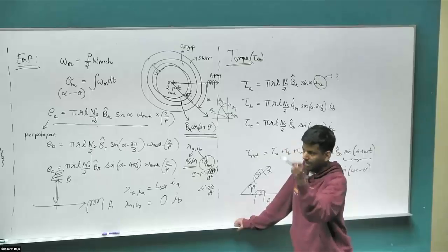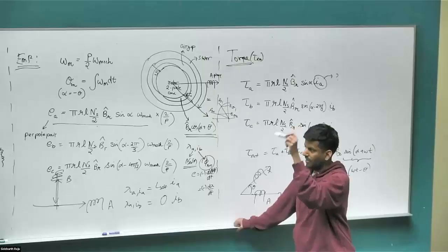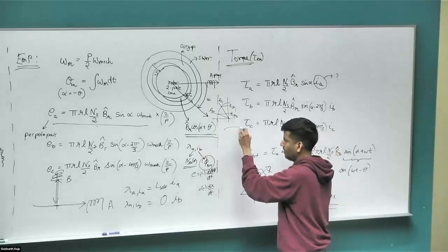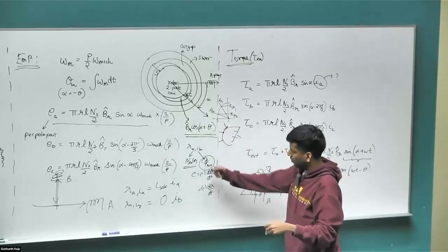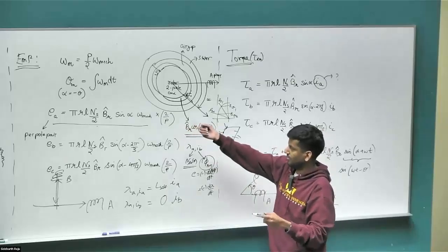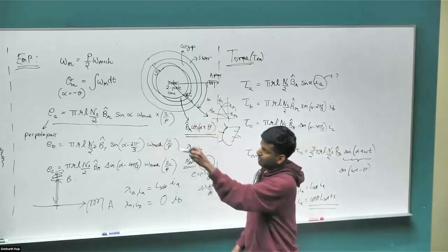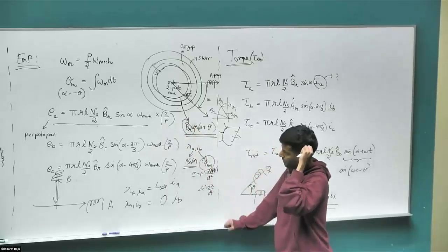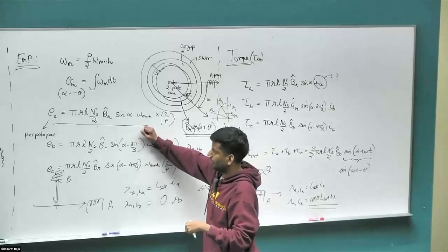And then once we know the magnetic field in the air gap, we can figure out the flux through any particular coil. Jonah gave the answer, right? Because you do the integral of B dot ds, whatever flux enters in will be the same as the flux leaving out, which is the part we derived here. This would be the same, and then we figure out the flux linkage. You go through this exact same process, but now instead of B of theta, the B field's magnetic field, use the rotor magnetic field, which has exactly the same profile. Just instead of the mu naught NSP divided by LG times I, you have this BR factor. So that's all, the derivation will be very simple. Just follow the procedure and you'll be able to get the same expression that I have right here.